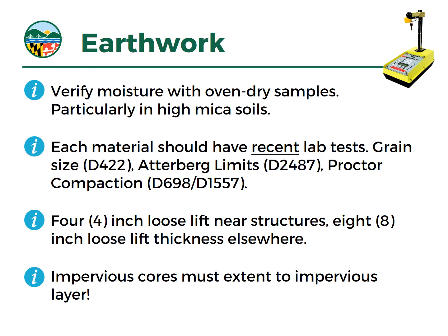It's just less energy. We're not trying to compact the soil too much, again, so that we don't create a brittle, more crack-prone structure. We would recommend placing soil materials in 8-inch loose lifts pretty much everywhere, unless you're close to a structure, when you might need to have smaller compaction equipment, and then a 4-inch lift is more appropriate.